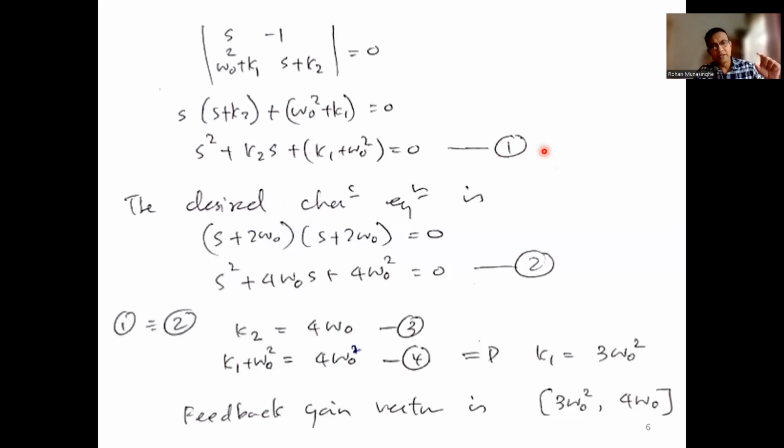And that feedback signal goes as a torque to the pendulum so that it will change the acceleration of the pendulum. Now see how this works, right? You measure position and velocity and then multiply with two gains, add them together and get the negative sign, produce a torque, right? And you're changing your pendulum.